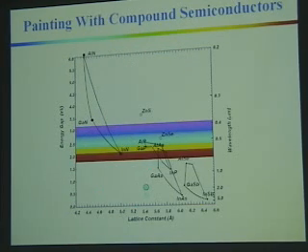The reason these two are important is, of course, the band gap energy tells us about the energy or the wavelength we might get from a particular light-emitting device, and the lattice parameter is important for us to be able to grow high-quality material. We generally want to be able to grow structures that are well lattice matched. And so I can take gallium nitride, which is just into the UV, alloy it with indium, and you can see I can get a wide range of the visible spectrum accessible. I can also alloy it with aluminum gallium indium to form a pseudo-quaternary that allows me to get this region in the spectrum as well as have a range of lattice parameters to be accessed.